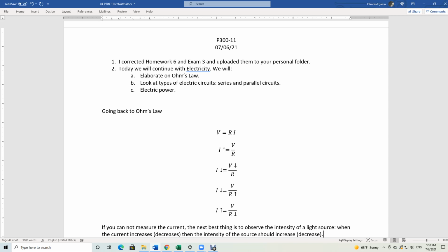Here you go. My LED is here. An LED has one leg that's longer than the other. The longer leg should be connected to the positive of the battery. Very important: an LED is a device that has a polarity. If you connect it in the other direction, the LED is not going to light up. So remember that. It's not getting secure there in the hole. Let me see if I can get it better. Oh yeah, now it's better.